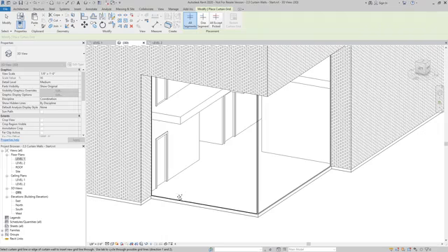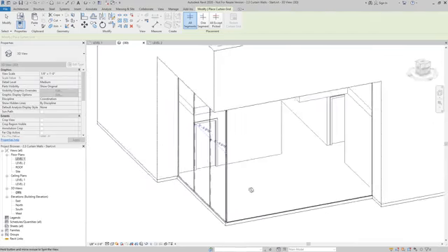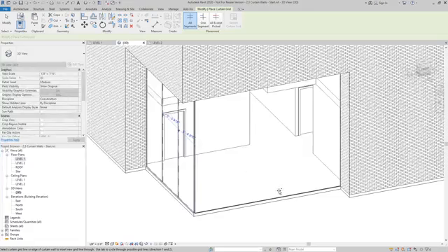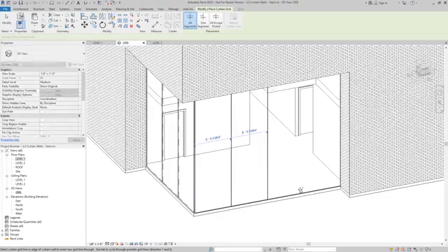What that means is I'm going to look across the bottom here, and as I move the mouse around, it'll lock in to certain points, and you can see it's already defining 1/3 of the curtain wall panel for me. And I can do the same thing, and it'll split this one in half. For this side, it'll be a little different. I can go in and I can find the center of the panel, and then I can allow it to divide it up into 4s.